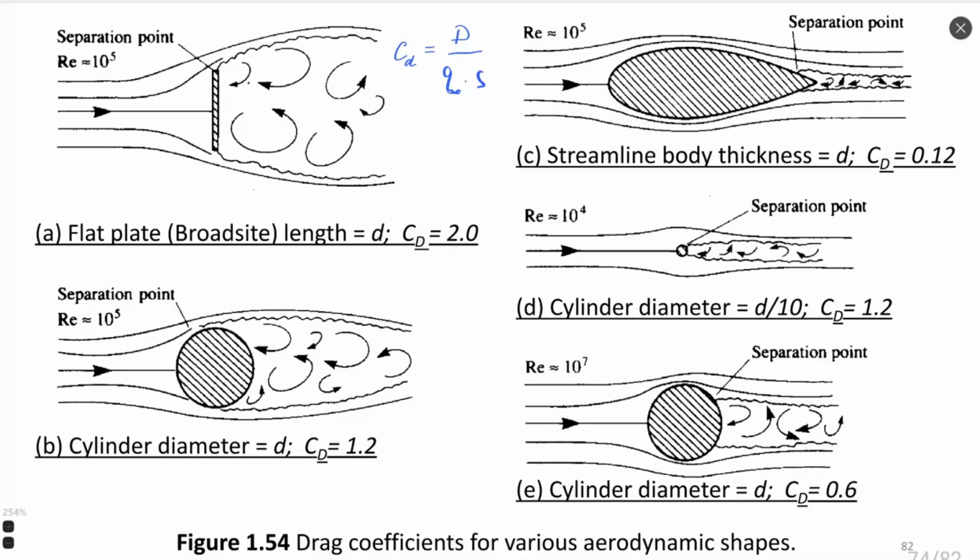In case of an airfoil, it will be the thickness of this airfoil. In some airfoils it is the chord size, but in this particular case, it's the thickness of the airfoil. And for a cylinder, okay, the diameter, and no other types of bodies. Quite simple bodies. Some bodies we can see here have a relatively big value of CD coefficient.